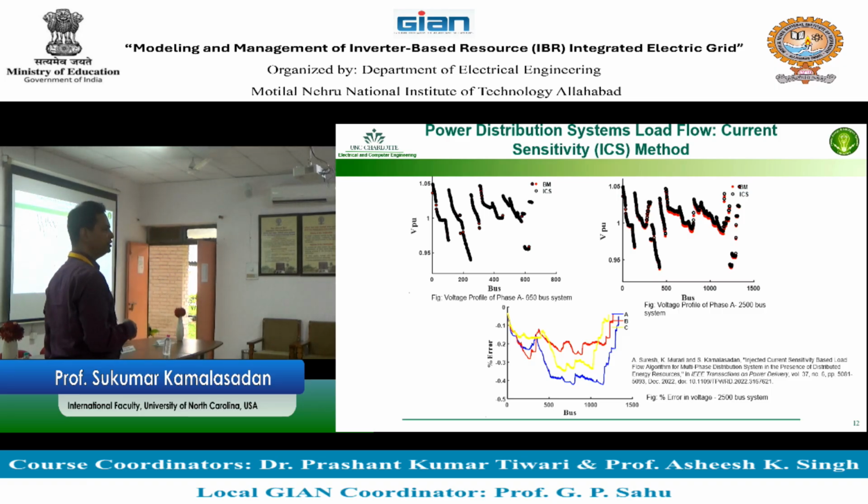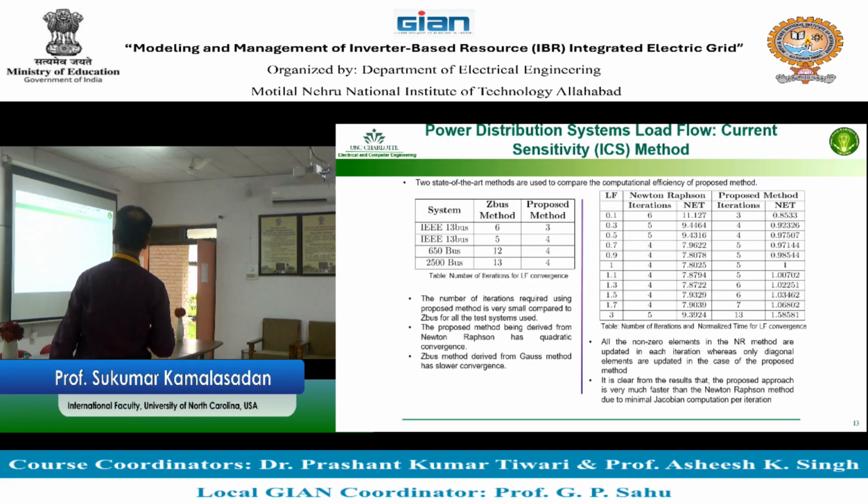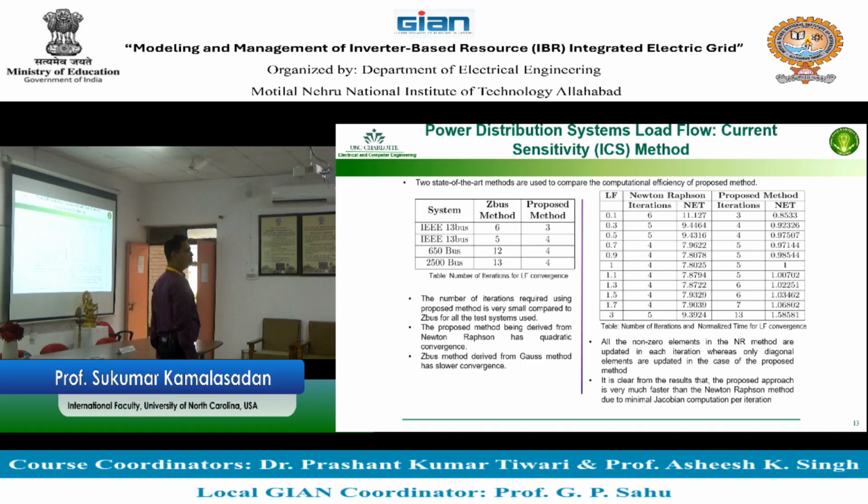Good. So I just wrapped up one more round of review on what we have done. You can actually compare this with a few different methods. This is a method that you can apply in a distribution system, also called Newton-Raphson. And this is another method where you can do current injection and then run it. The good news about current injection is that this current injection model can be used for a transmission system too, which means that you can make one power flow for the transmission system and the distribution system, even though it is a little difficult.